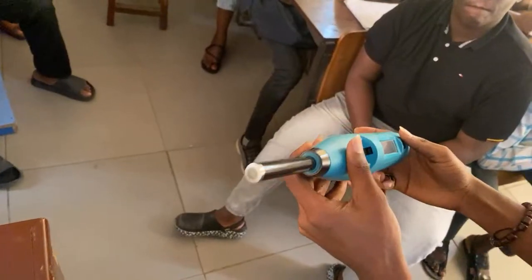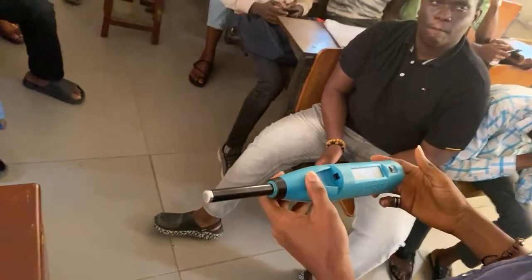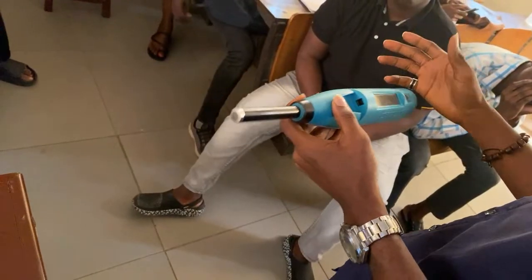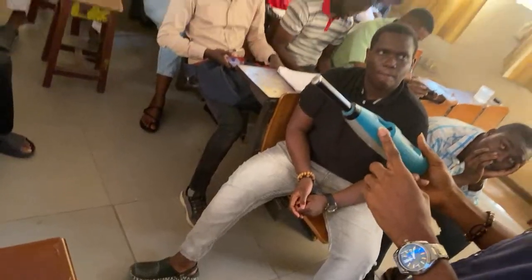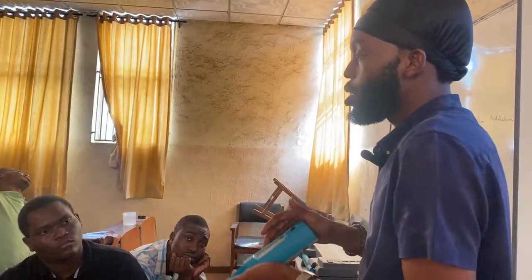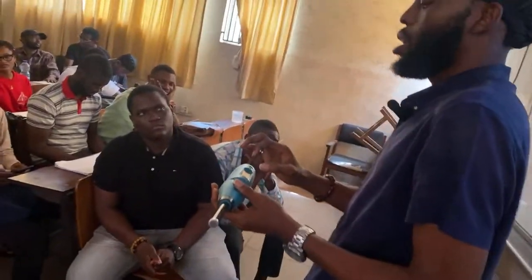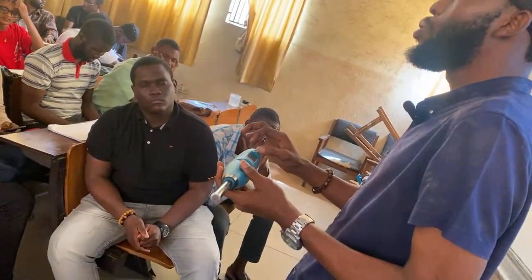When you want to test, beforehand you have to calibrate the Schmidt hammer, and there's a calibration anvil for that. I didn't bring it because it's quite heavy, but movable though. When we use the Schmidt hammer on the anvil, there's a particular rebound number it should give us if the Schmidt hammer is still very good.